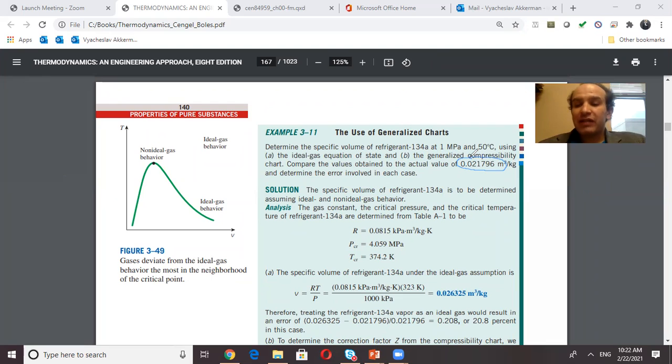And now I will behave like a not very accurate person. So I'm thinking, may I employ ideal gas or not? What should I check to see if I can employ ideal gas or not? I should find Z, exactly. So how to find Z? There are actually two ways. One way is the following. If you have this value, you can simply write that Z is PV over RT, and here you substitute this V value and calculate.